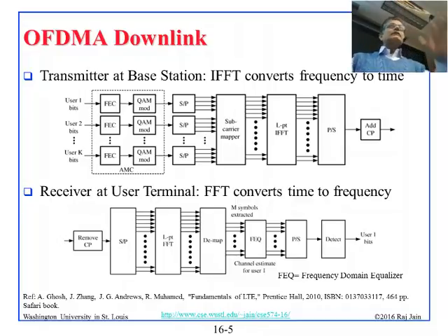So this is the reason I have to explain. One thing you have to understand is that, the last time we had this research seminar, somebody asked, if you have to change your frequencies every few microseconds, don't you have to change your radio? No, nothing in the radio is changed. The radio receives all 1024 subcarriers on every user, on every phone. It's just that which one you have to receive is in the map.